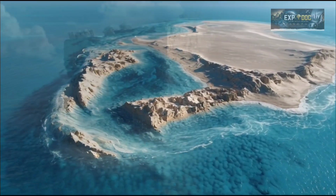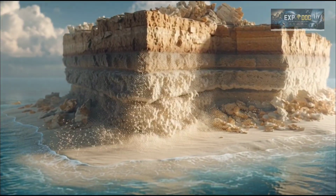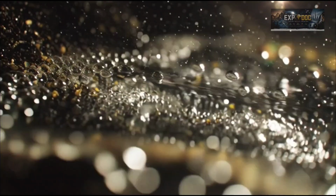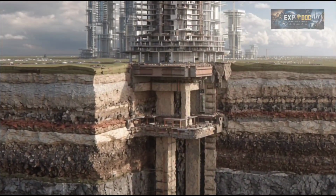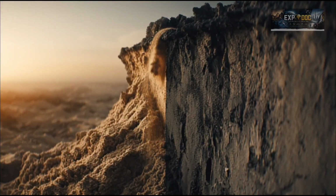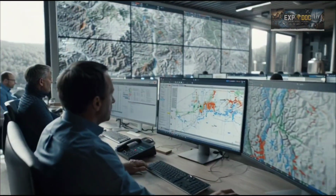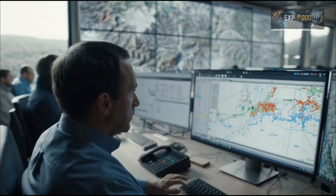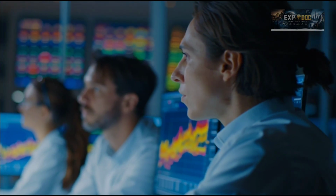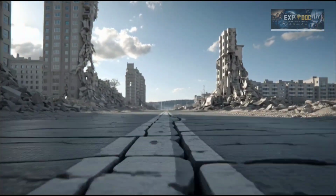Simply placing millions of tons of sand is not enough. Engineers must ensure that this newly created land remains stable for decades, or even centuries. The biggest challenge is that freshly reclaimed sand contains large amounts of water and trapped air. Under its enormous weight, the sand gradually compresses, causing the surface of the island to slowly settle. If buildings, roads, or airport runways are constructed too soon, they may develop cracks or even suffer structural damage within just a few years. To prevent these problems, engineers use advanced ground improvement techniques to accelerate soil consolidation.